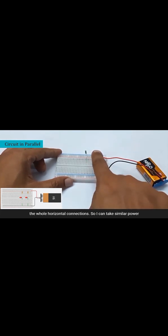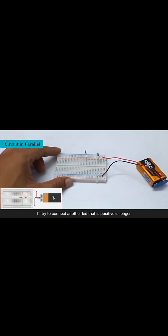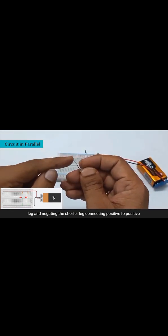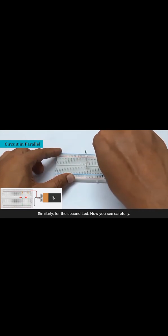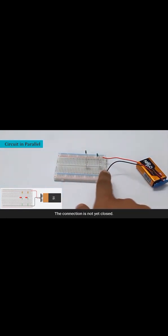As you can see, the same positive potential is flowing through the whole horizontal connection. So I can take similar power from the second resistor as well. I'll connect another LED, where the positive is the longer leg and negative the shorter leg. Connecting positive to positive side. Again similarly for the second LED. Now if you see carefully, the connection is not yet closed.